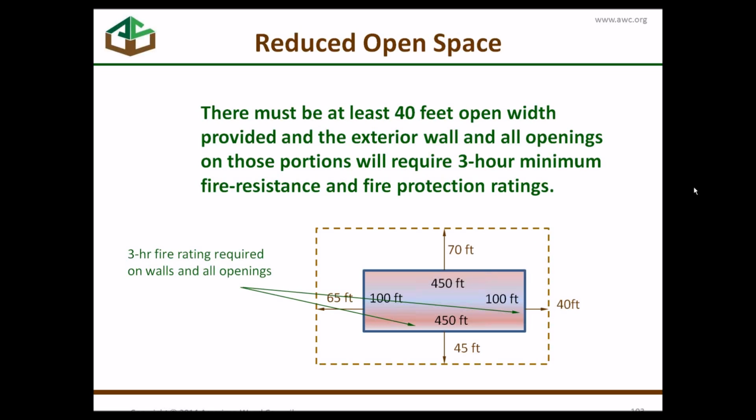So therefore, open space could not be a body of water, like a lake behind the building. That would not be considered open space. However, a parking lot is considered open space. Most jurisdictions would say if you had a stand of trees that were very dense, if there was no firefighter access on that side of the building, those are the kind of things you have to be careful of.